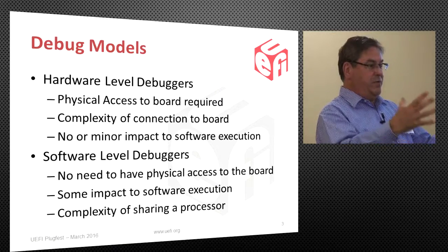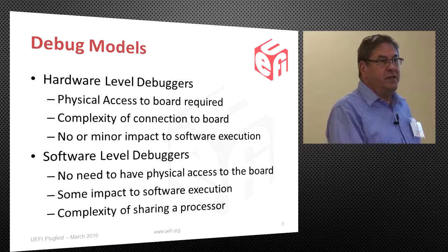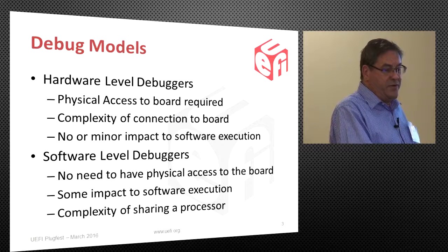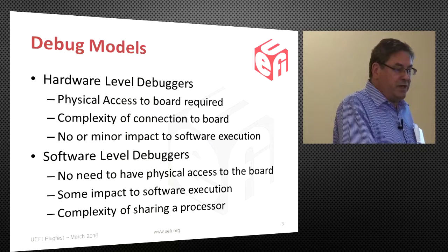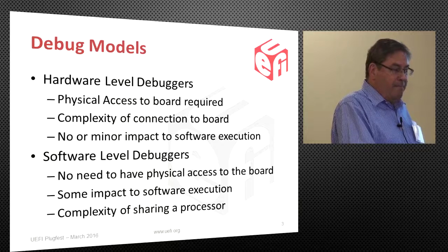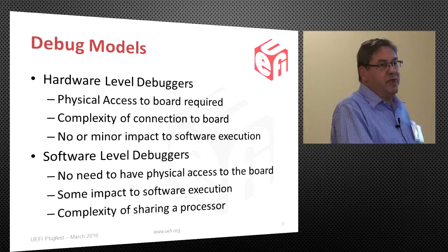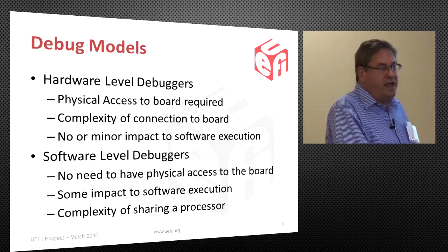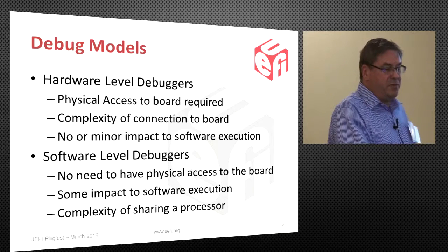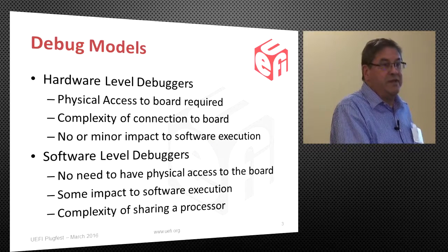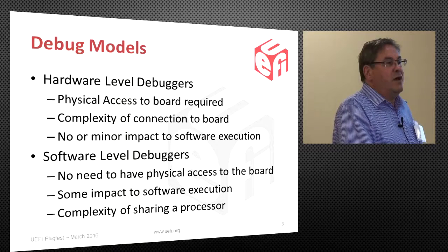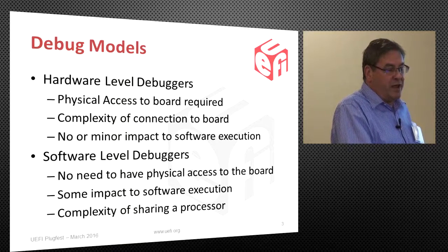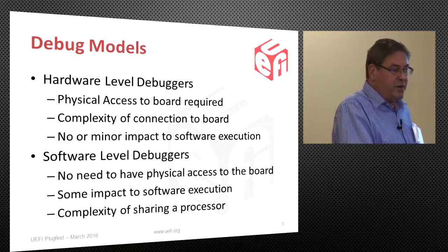So you would end up with this massive connection that you'd want to make to the board to be able to do any sort of reasonable debug. The good thing about it is it had almost no impact on the software that was running. Occasionally it would have a little bit, but for the most part, you could pretty much guarantee that things would work on a board without the debugger and on a board with the debugger.